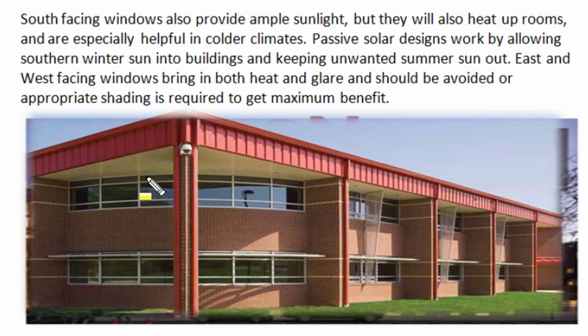In good solar passive design, we should avoid direct sunlight from east or especially west facing fenestration, as west facing windows bring both heat and glare, and that should be avoided, or we must use appropriate shading to restrict entry of heat from the west face.